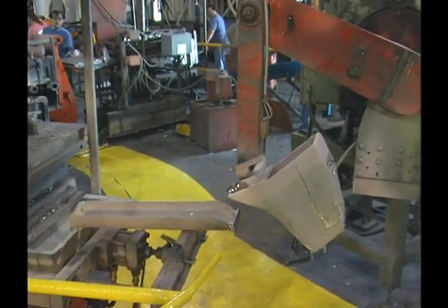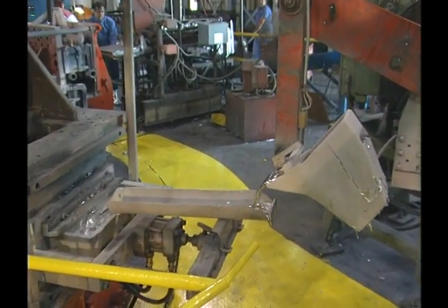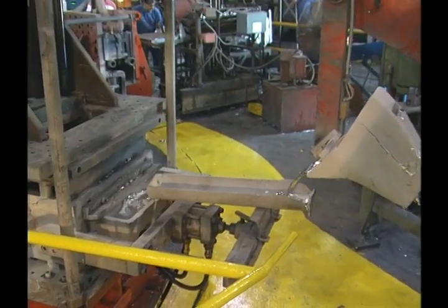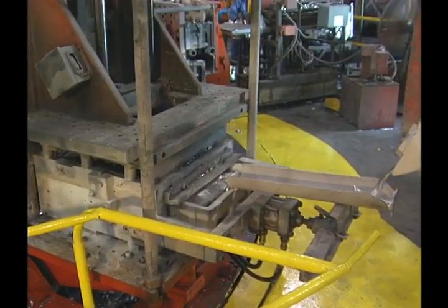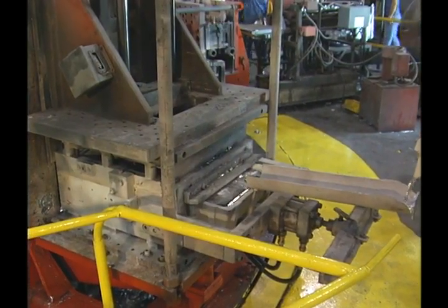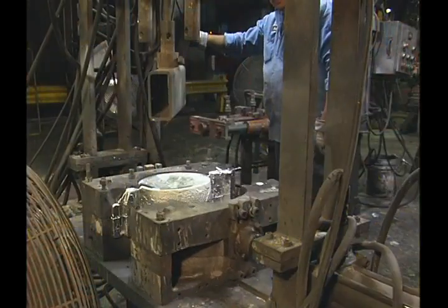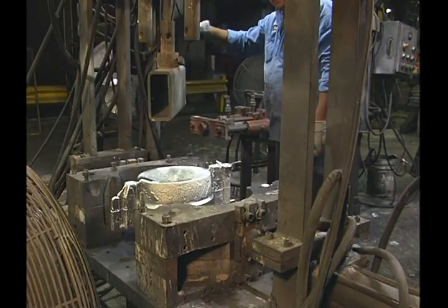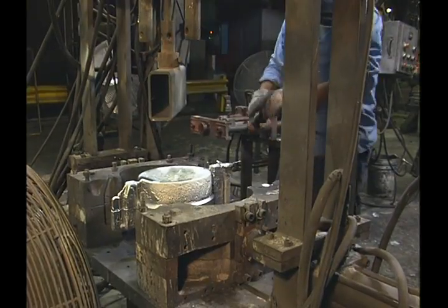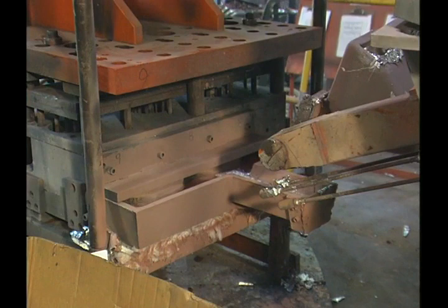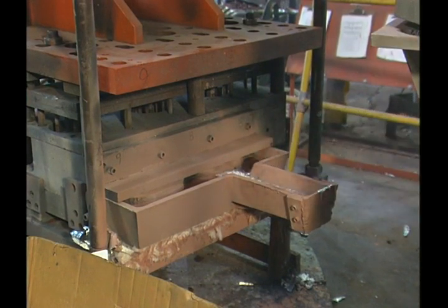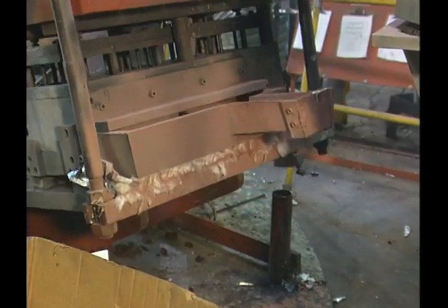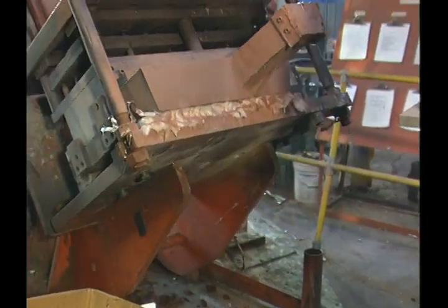Permanent molds are typically preheated and maintained at required temperature for casting. This helps facilitate metal flow and reduces thermal damage to the mold. The parting line of the mold may be arranged vertically to ease removal of the casting. But since some metals are better cast in horizontal molds, tilting mechanisms can reposition the mold vertically after pouring.